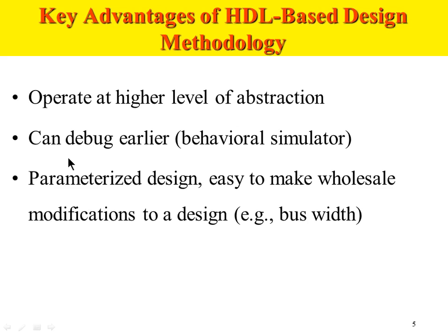Another advantage is we can debug earlier. So this is a very key advantage. When you do design in Verilog, you can write a test bench and you can debug the design. Make sure there are no errors whatsoever at the simulation stage itself. If there are any errors, you can fix the errors at the simulation stage and then go on for the backend process. There is a certain thing called parameterized design when we use Verilog, where we can quickly make whole scale or large scale changes, modifications to a design.